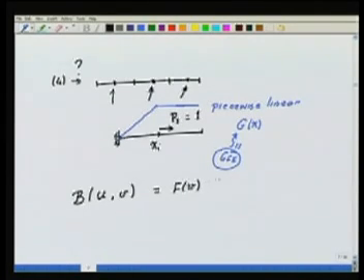I am simply recapping, for all admissible v's. Now we know what we mean by admissible: v at the point where the geometric condition is given is 0. Similarly, we also know that if this is true for the exact solution for any v, then it should also be true for the so-called v finite element,